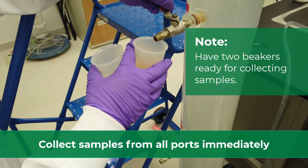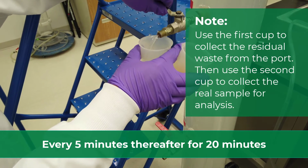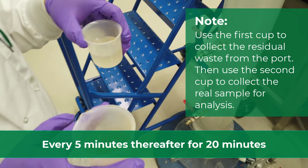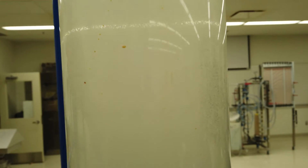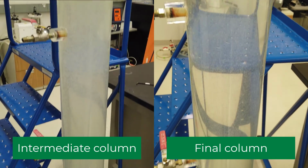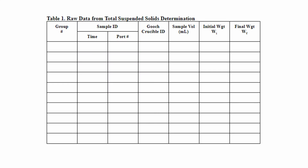Collect samples from each of the 5 sample ports immediately after the air is shut off and every 5 minutes thereafter for 20 minutes, i.e. samples collected at T0, T5, T10, T15, and T20. In the early stages, withdraw approximately 25 milliliters of sample from each port. As the floc thickens in the lower ports and the water clears in the upper ports, smaller and larger samples may be required respectively. Prepare a table in your notebook, similar to Table 1 from the lab handout.